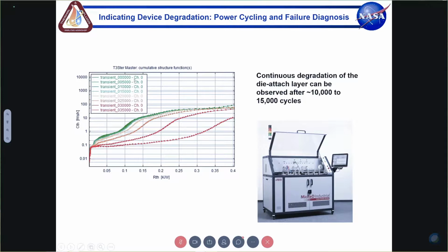Basically, the colorful areas are temperature gradients, and in key areas such as the die attach or the base plate solder, we have very high temperature gradients leading to high thermal stress. And that can break the die attach layer.